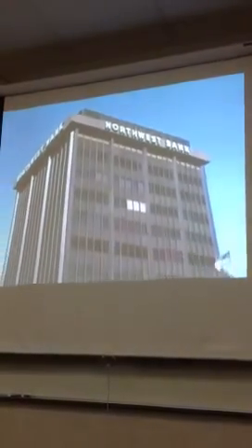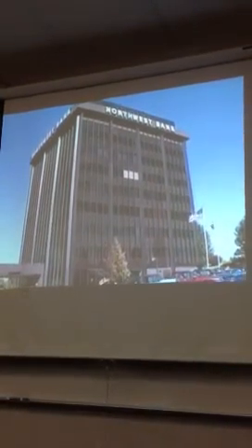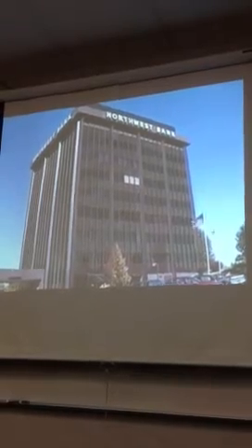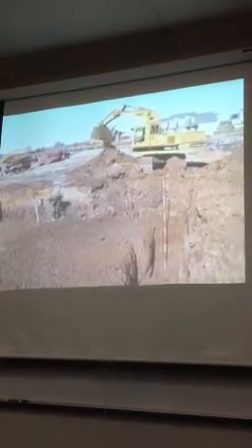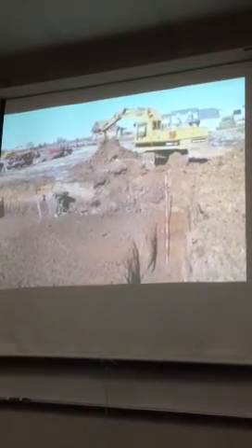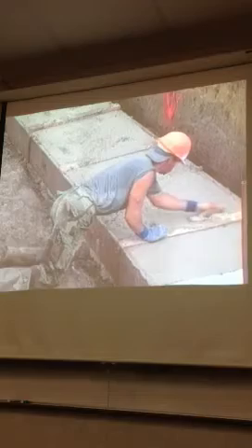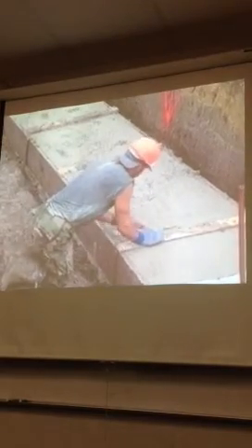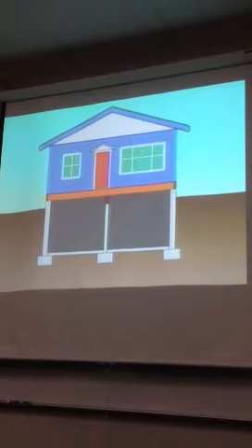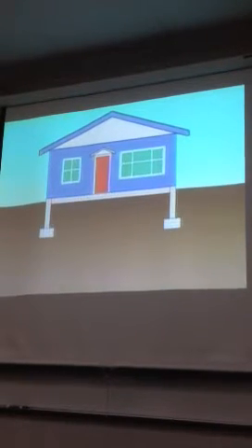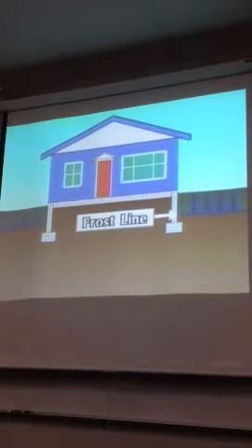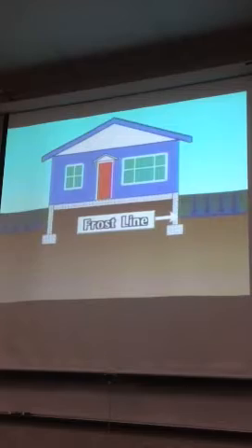Well, depending on the soil, larger, heavier structures tend to be supported by either spread or pile foundations. If the soil is hard or near bedrock, a major structure may be built on a spread foundation, which places the weight of the structure on thick support walls. And depending on the depth of these walls, the space they create may serve as either a basement or a crawl space. However, in climates where the ground freezes in winter, they must be set below the frost line so that they won't shift when the ground shifts.